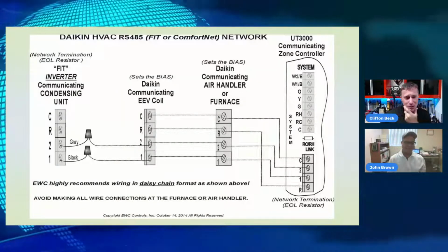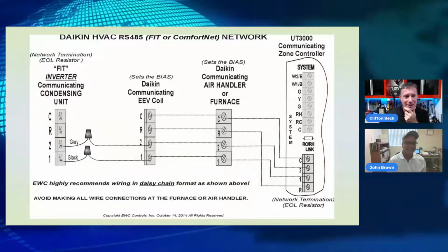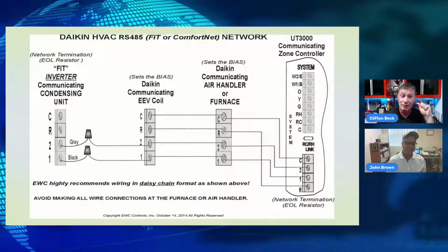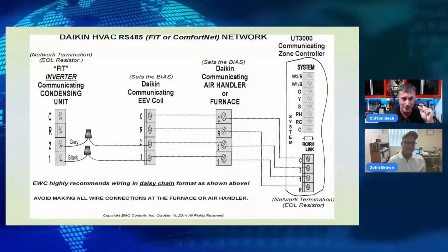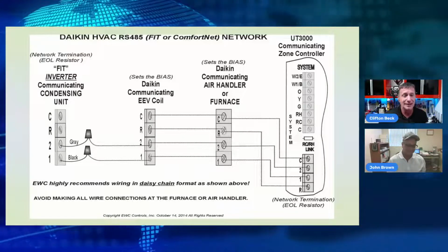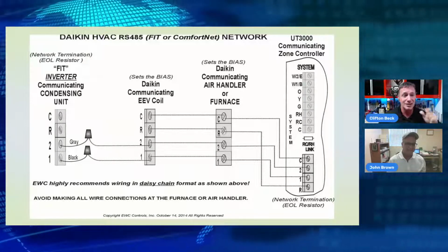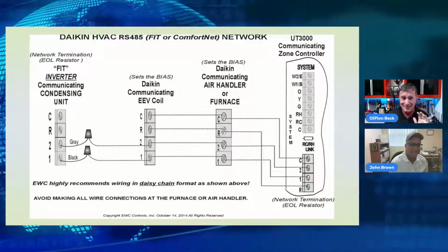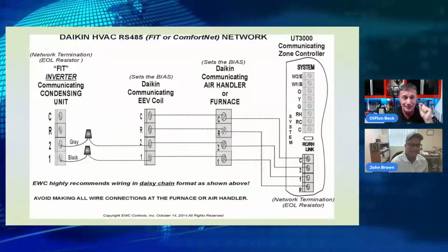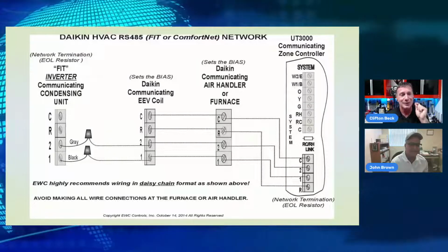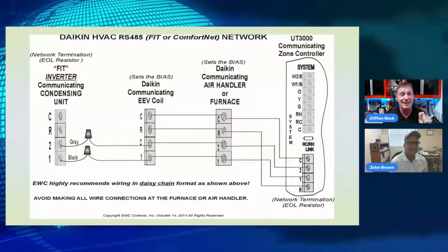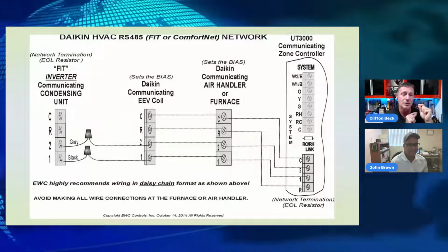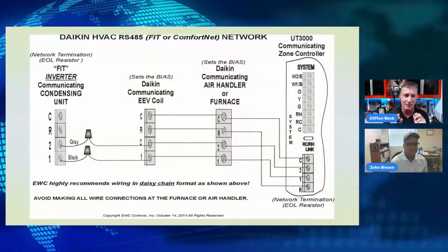And I go, what are you doing when you put your digital gauges on a piece of equipment? You are using, by the way, a 5-volt DC pressure transducer to calculate the pressure of your suction so that your gauges have a number to work with. And we're also using a 5-volt DC potential temperature reading that we're going to measure the suction line. And now we have two mathematical numbers that we can calculate superheat with.